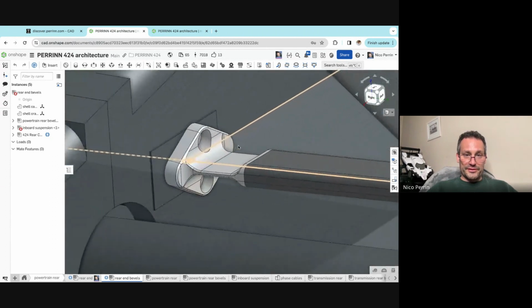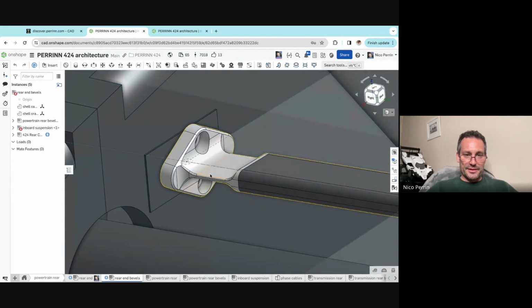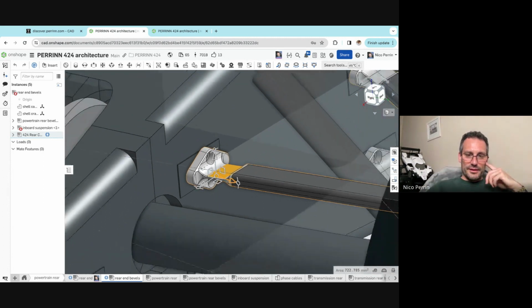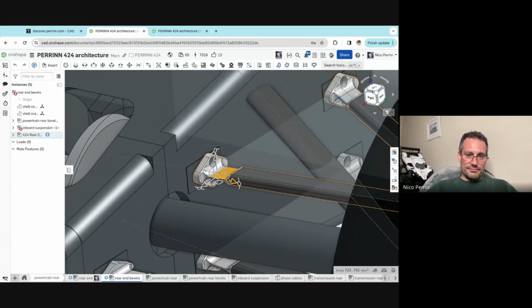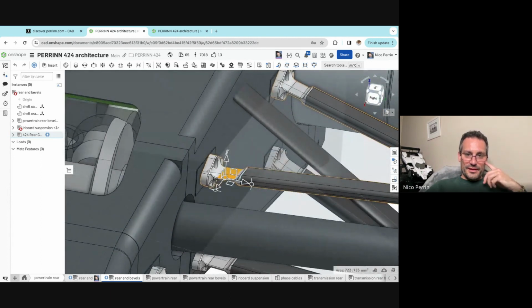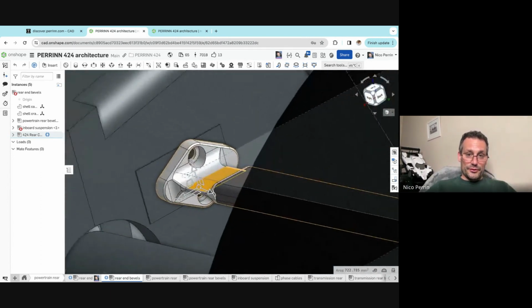went into more detail. You can see we wanted to understand how the suspension flexures. Here we have blades that will deform, like on a Formula One car. So the wishbones are moving not around a spherical joint, but we have basically a flexure, and we have this steel part that will deform. It's lighter, and it's just a lighter way to do it. And in this case, the model is fairly accurate.